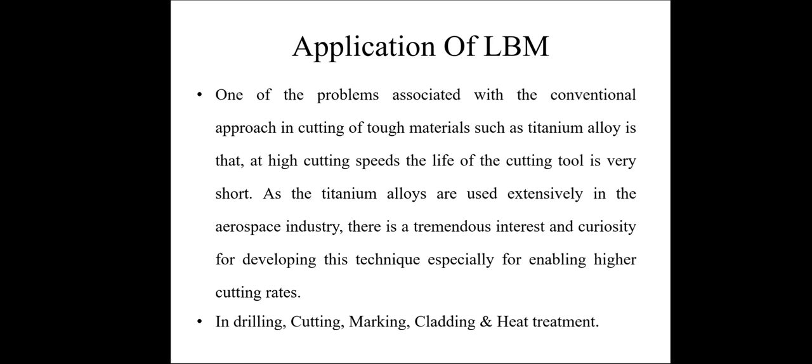Next one is cladding. It is done in the application where only a portion of work piece area needs to be protected from wear or corrosion without requiring the whole part to be made of high cost material. This laser beam machining is also used for heat treatment.